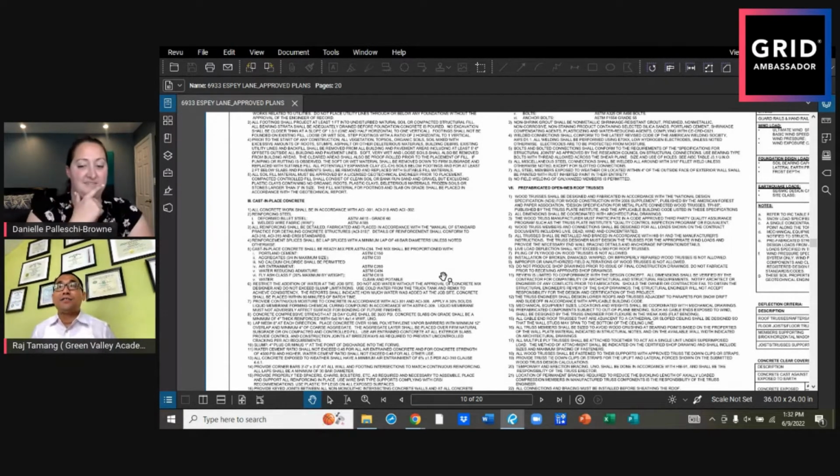That's why all these trucks you see running around, concrete trucks, come from the batch plant. The batch plant produces all this concrete, and the trucks bring it to the site. Sometimes you mix on the site, but that's not as accurate. The trucks are more accurate because it's done in a controlled environment in their batch plant, and the truck brings the concrete to the site.